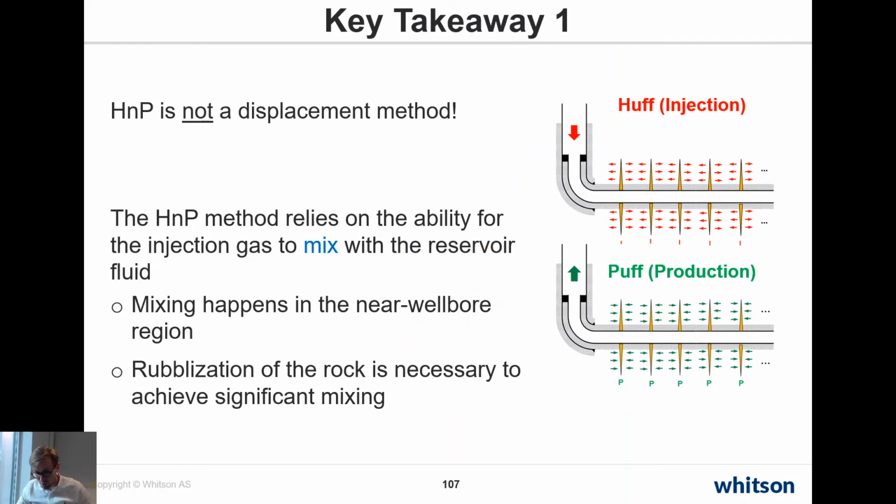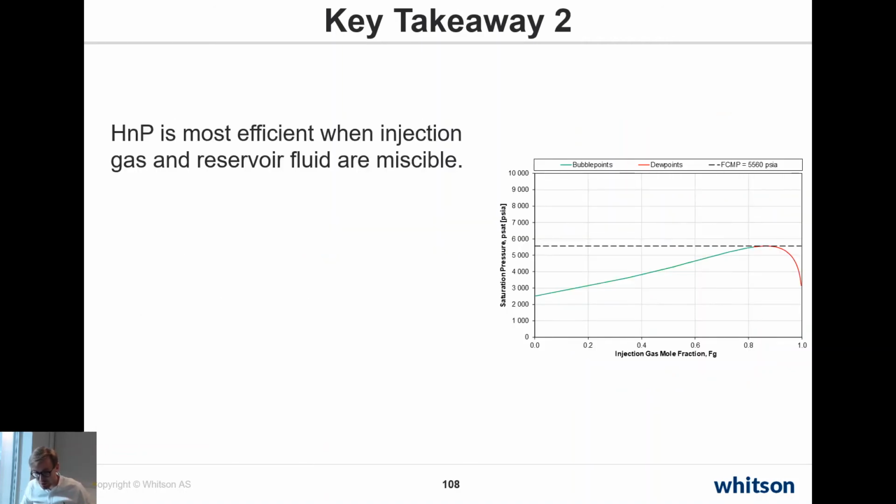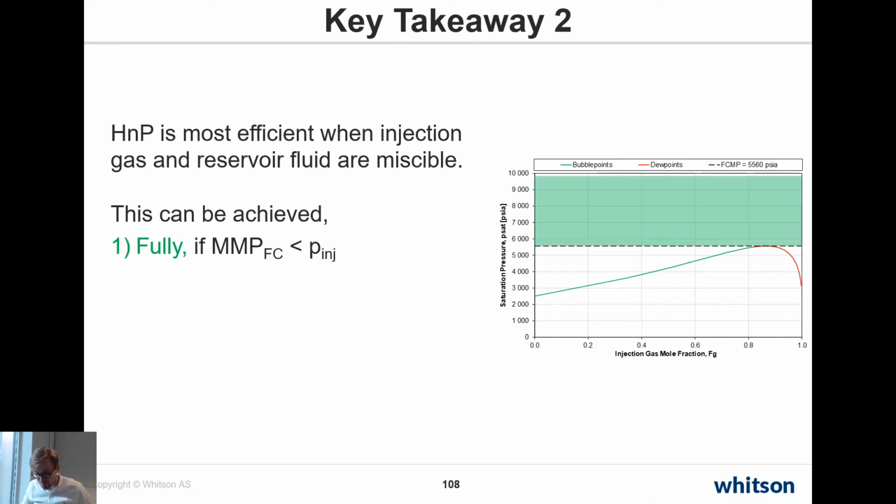So key takeaway 1: the gas huff and puff process is not a displacement process. It relies on the ability of the injection gas to mix with the reservoir fluid. And mixing happens in the near-fracture region, where rubblization of the rock is necessary to achieve significant mixing. Key takeaway 2: huff and puff is most efficient when injection gas and reservoir fluid are miscible.